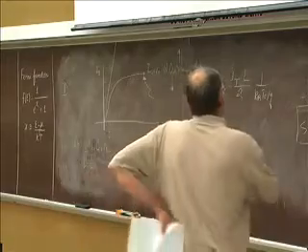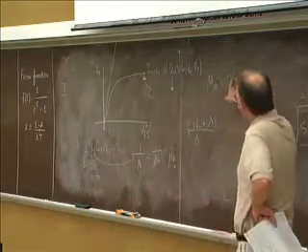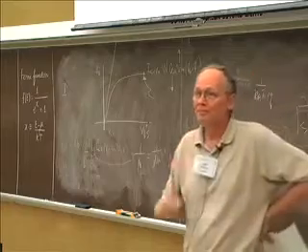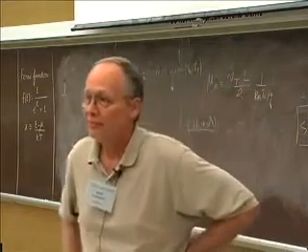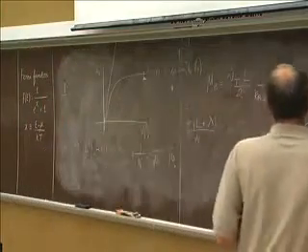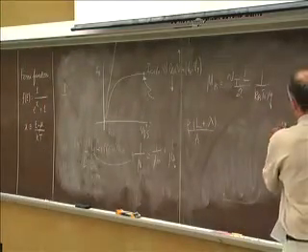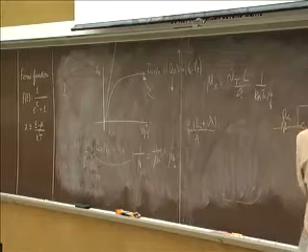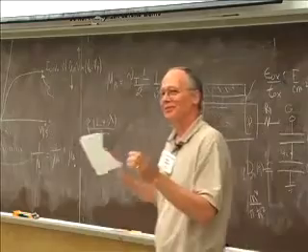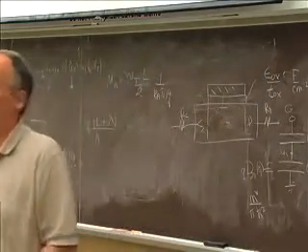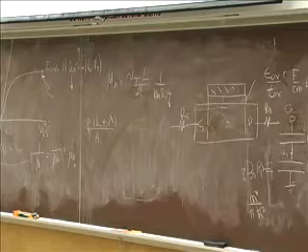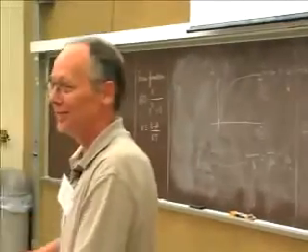Yeah, so for a given channel length, I guess this ballistic velocity will be higher, right? But then there's an issue of all the extraneous resistance, all of this parasitic source-drain resistance. Some of these practical issues are very challenging because you're thinning everything down, and you're making all of these parasitic resistances higher.